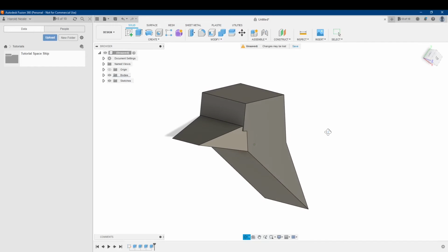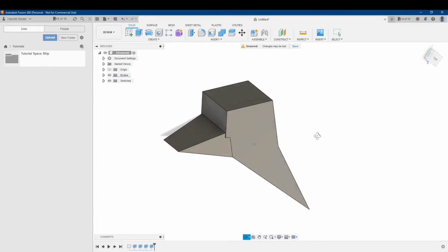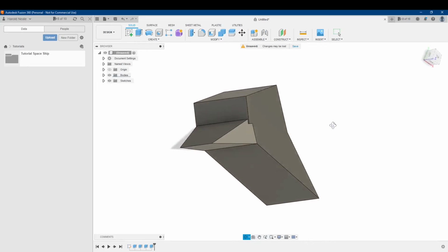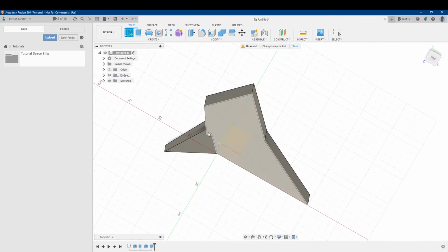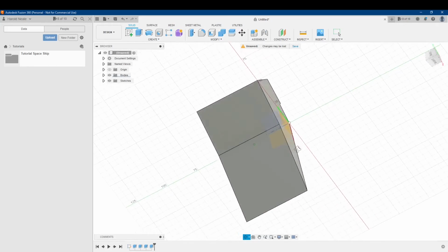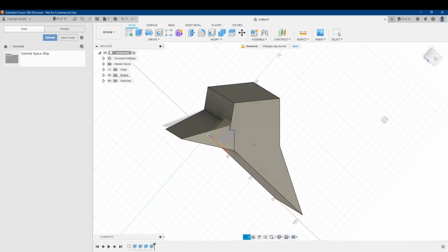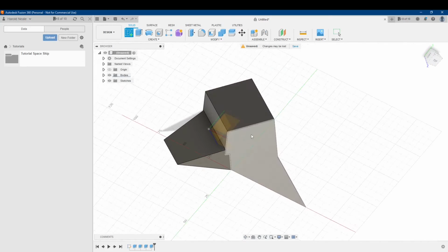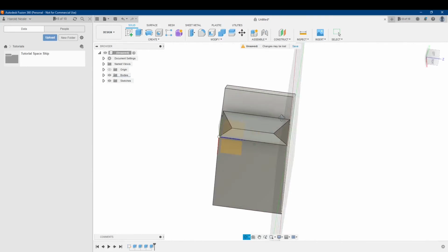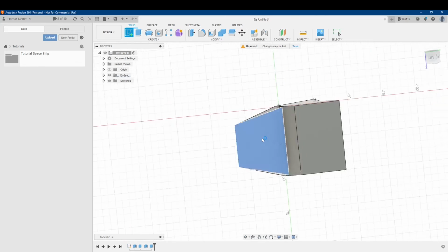Now if you wanted to create a more complex shape on your 3D model than your existing profiles, then you can make a new sketch. Now, just like how I made a new sketch on one of these 3 planes, you can make a sketch on one of these profiles, or body faces. So maybe I want to make a new sketch right here.